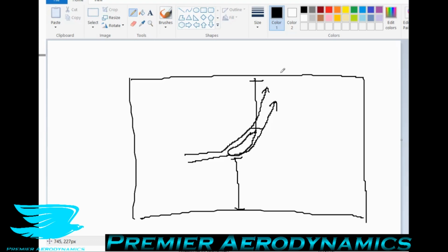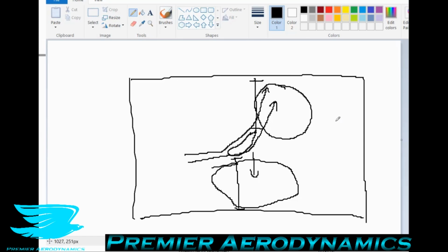So because below the wing, not much is really going to be going on here, you can probably put this closer to the wall to then move it away from this top surface to allow the flow coming off of the wing to develop properly or better and not hit this top part. Because depending on the boundary layer conditions you put on here, which is usually going to be a symmetry plane or whatever, it's going to hinder the development of this wake, which will then impact the upstream airfoil and affect its flow conditions as well as performance.